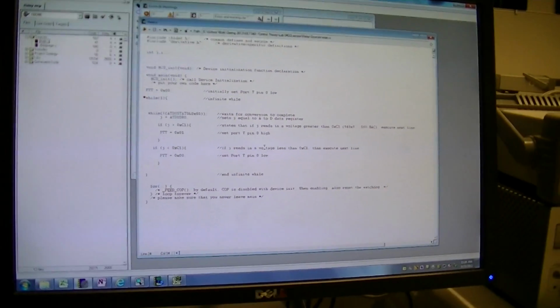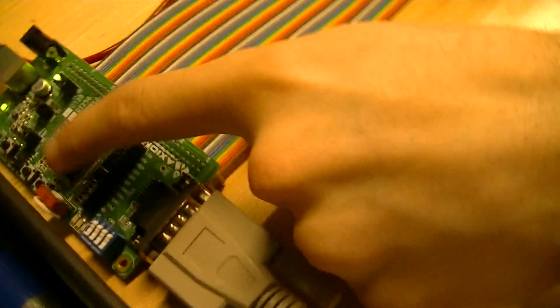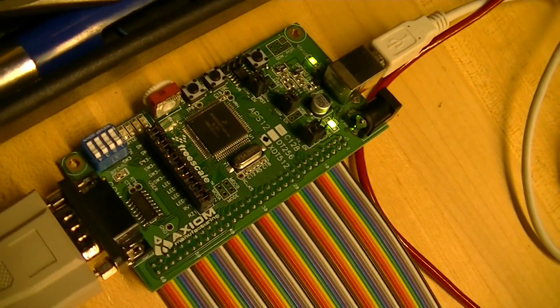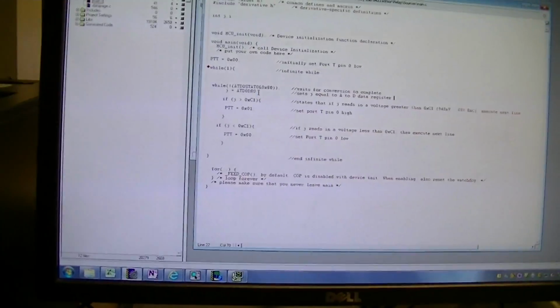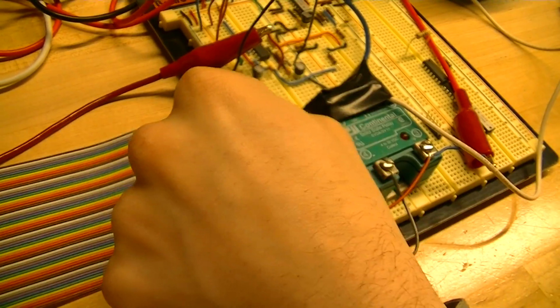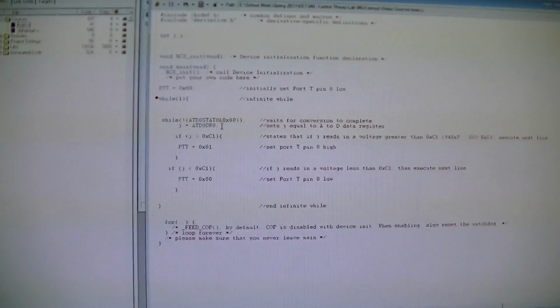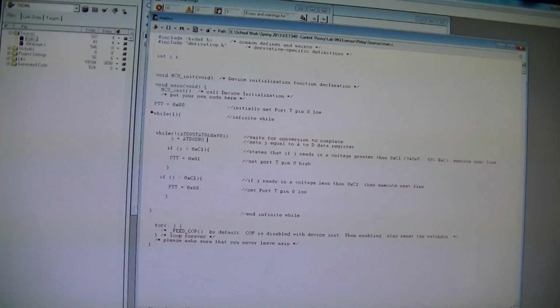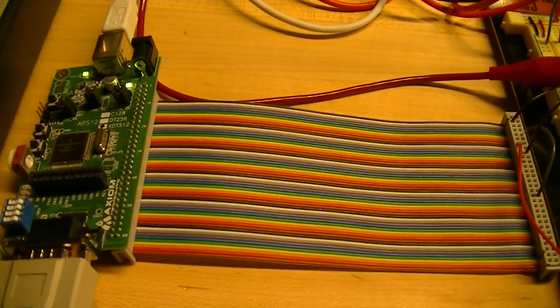Right. So this program actually runs on the microcontroller here. This is an HC12 board. This program is running on this CMB chip right here. And this is my A to D data register. This purple wire here, I'm feeding the output of my circuit into the microcontroller. Right, and you showed me the conditioning circuit on your spreadsheet, right? Right, yep. It amplifies the signal and conditions it so that the A to D converter can process the information.